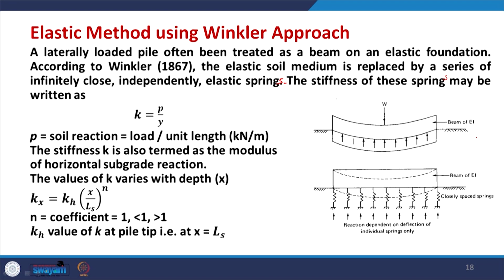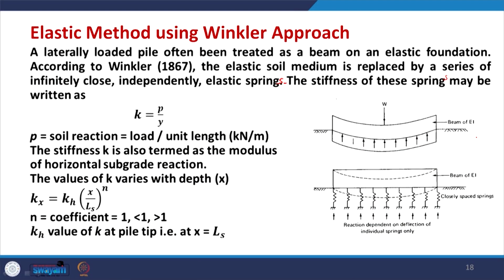If you keep the same deflection and the soil properties are also the same, then P will also be the same throughout, but if the deflection is not expected to be the same, then P is going to be more at the center for the same soil property. If I assume that all the springs have the same value of K, then naturally y is increasing at the center. So, you will get more value of soil reaction at the center, depending on that.